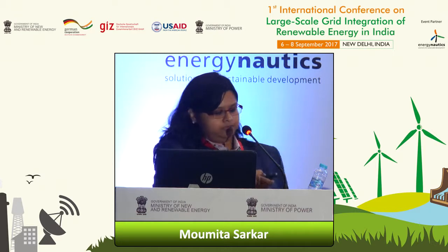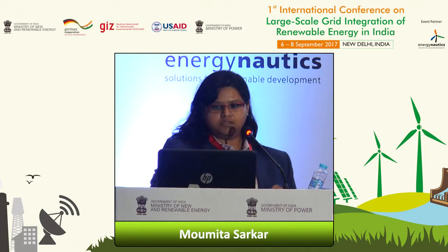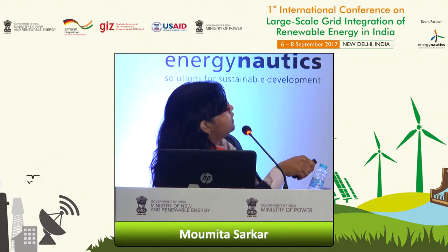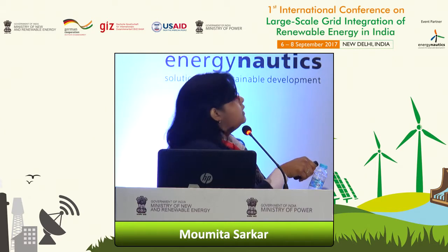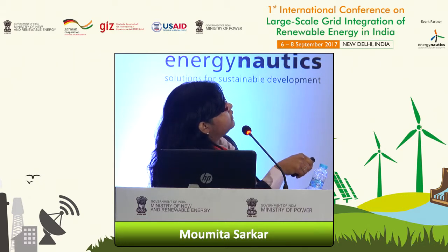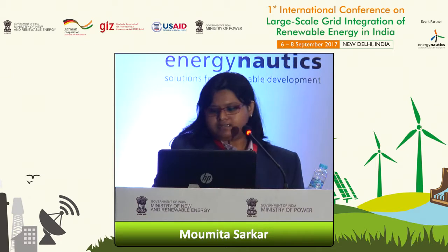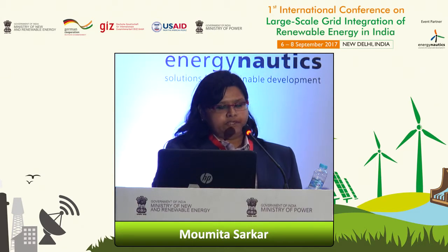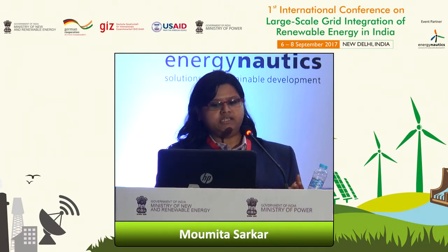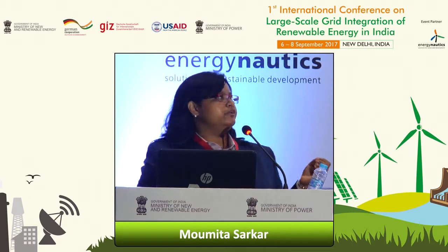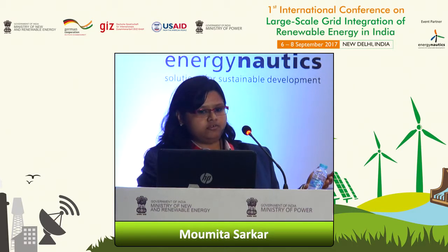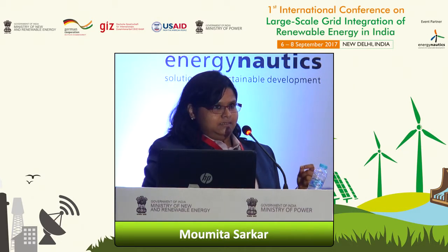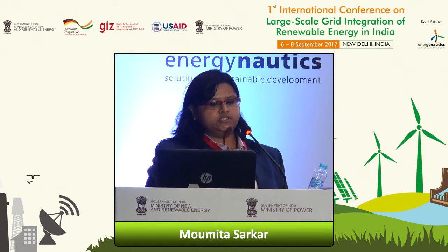If we go back to this one, we can see that when there is 1 pu active power output from the power plant, the reactive power can go up to 0.228 pu. So we can see that there is still some capability of the wind power plant to provide additional reactive power support. But if we are using only local voltage control, probably this capability is not fully utilized.